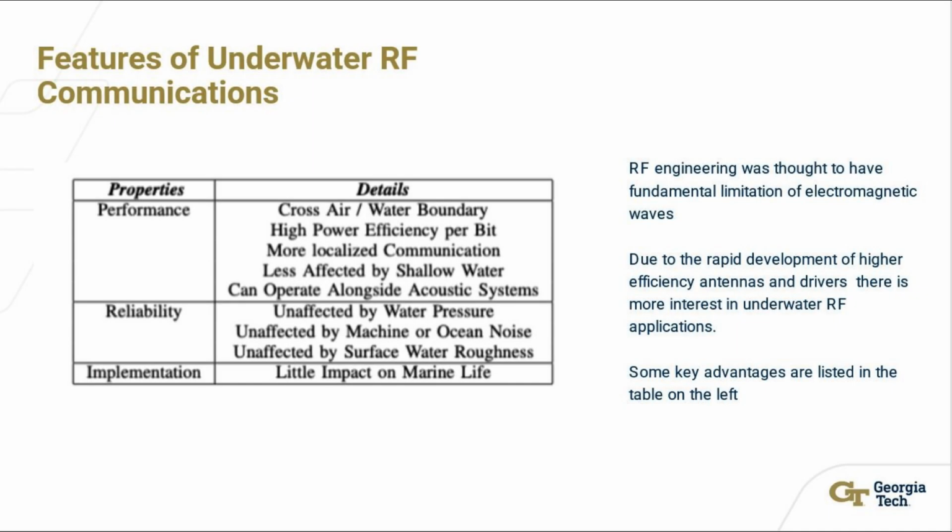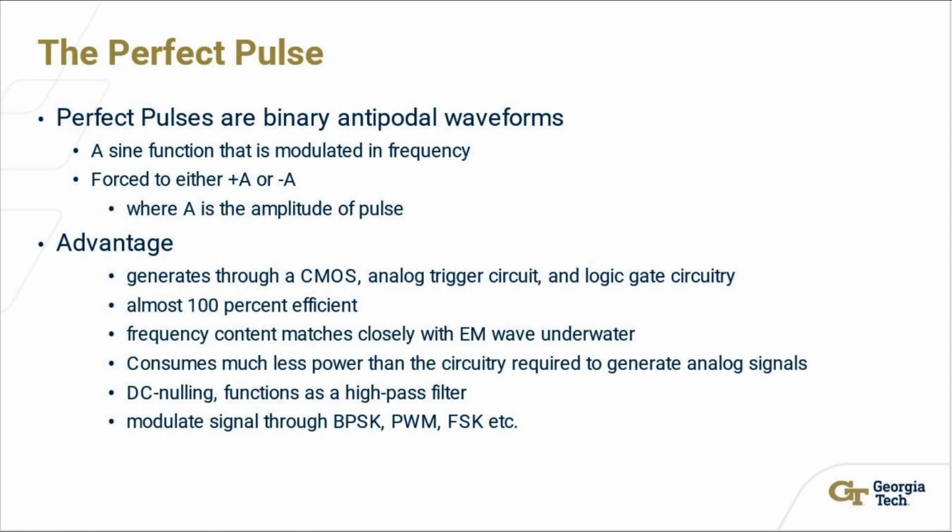And then you have the features of underwater RF communications, and these are just properties and details about the reliability, performance, and implementation of RF engineering, and how, due to rapid development of higher efficiency antennas, there is more interest in underwater RF applications now, and some key advantages are listed on the slides. After understanding the current status of research and challenges in underwater communication, this design seeks to use a perfect pulse to modulate incoming signals instead of using a traditional sound wave as frequency carrier.